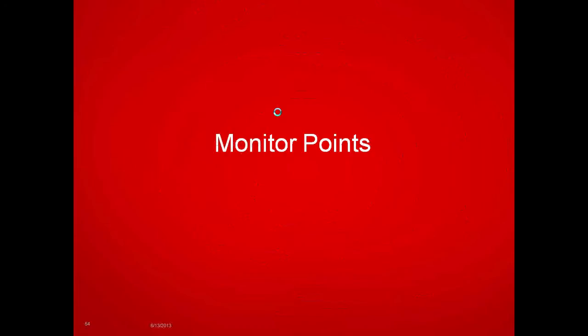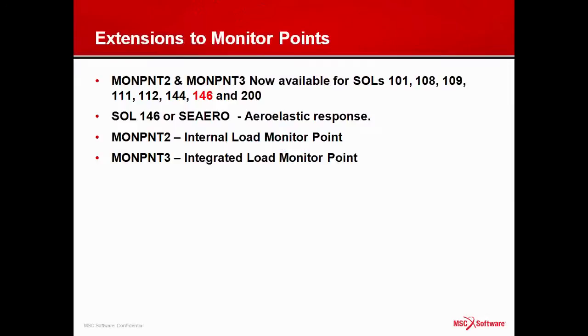Something that's related to dynamics, or certainly was first implemented for dynamics, is something called monitor points. Monitor points is something I think is underutilized with MSC Nastran, but it's a very powerful tool because it allows you to look at a single piece of output and get a lot of physics out of it. It was available for a variety of solution sequences. What we've done in 2013 is we've added it to another solution sequence.